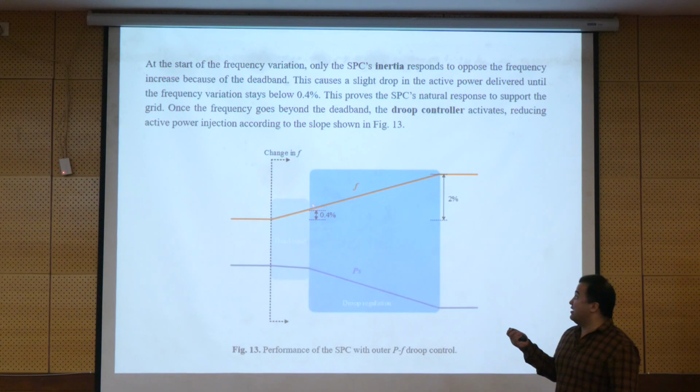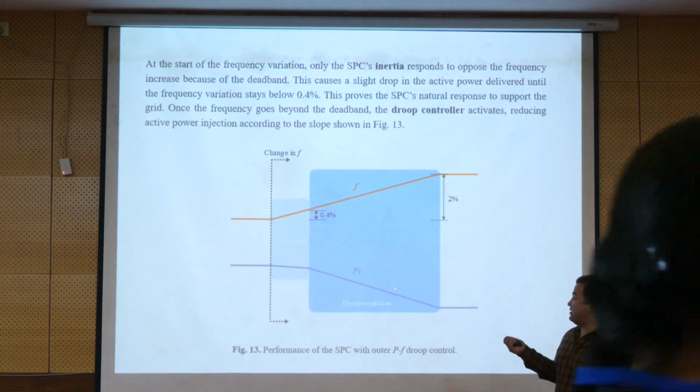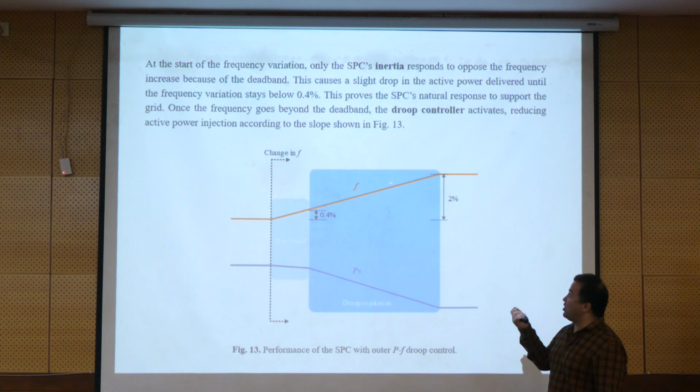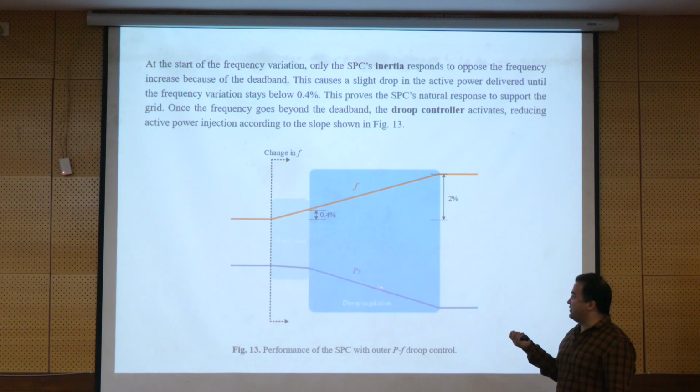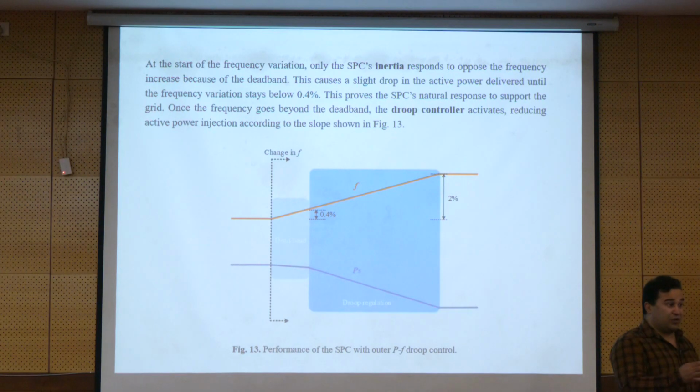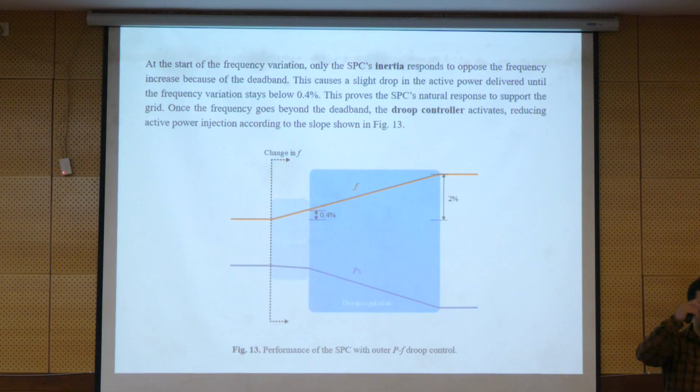But when we pass this dead band and the regulation changes, and the frequency goes up, we see that the active power goes down. So by this, we balance the frequency by reducing the active power. For example, if the load is less, then we reduce the value of the active power, updating our reference value. By this, from 10 to 8, again we get back the right frequency.